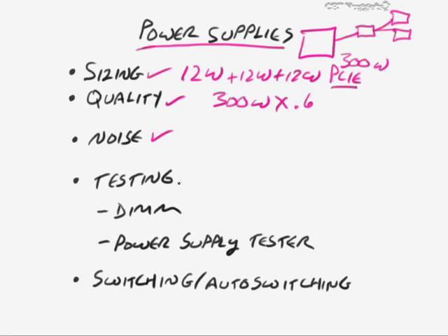Also, testing of a power supply. If you suspect that there's a problem, such as a computer that just spontaneously reboots sometimes, when this happens, it might be that the power supply has insufficient power to do all that the user needs. Maybe they're running a highly demanding application that is very disk-intensive, for example, and when those hard drives start to spin, which are pretty high voltage, then it could overwhelm the power supply and the power OK signal drops and the system reboots. Very inconvenient. So that really goes to sizing more than it does testing. So make sure that it's properly sized.